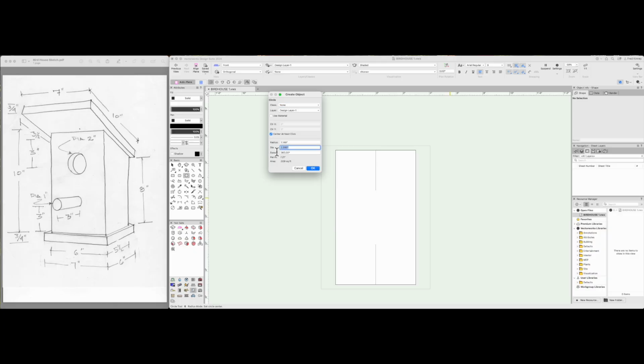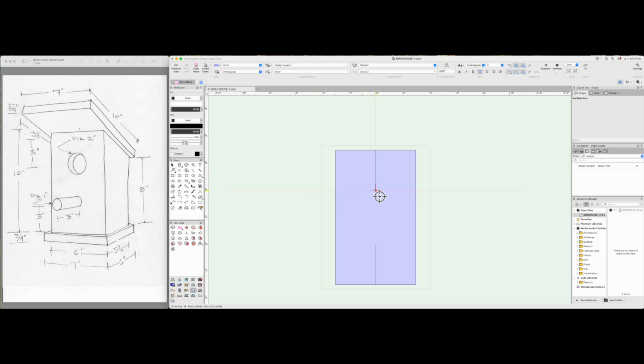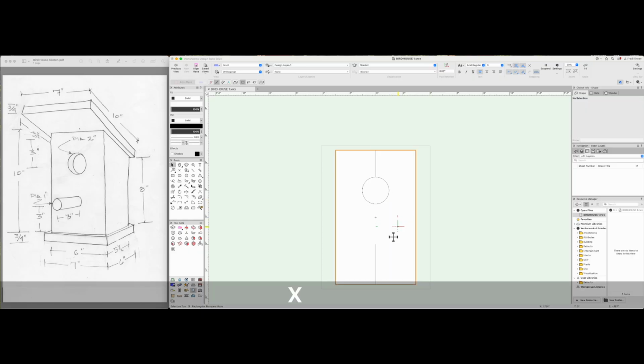We're going to go into the radius. In this case, the radius is called out, or actually in this case, the diameter. The diameter is called out as 2 inches. Just hit 2. Again, the default for Vectorworks currently, the way it's set up, is inches are the default. You can hit OK. Your little sights, you're going to go like this, and you can tell it's going to naturally want to go there. Once you get close, it knows where you want to go. There is our circle that is 2 inches in diameter. Great. We can do the same thing down here.